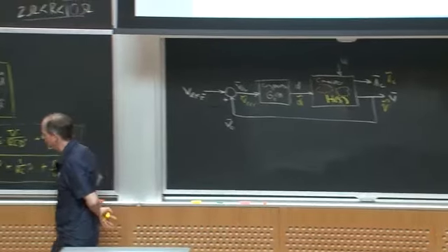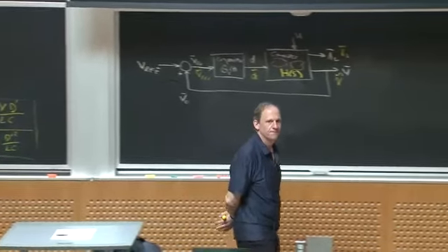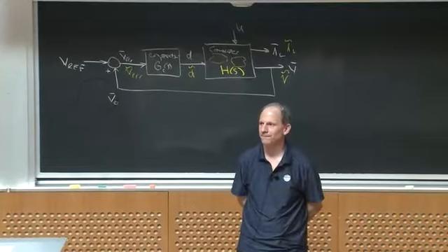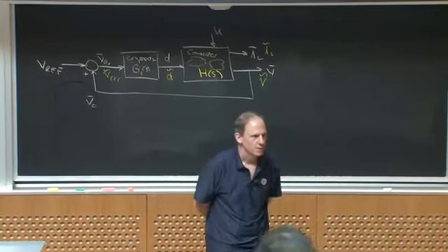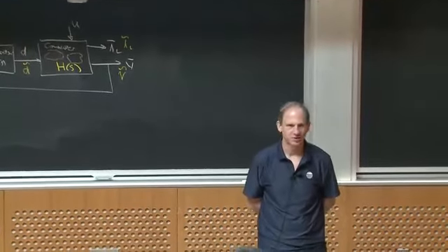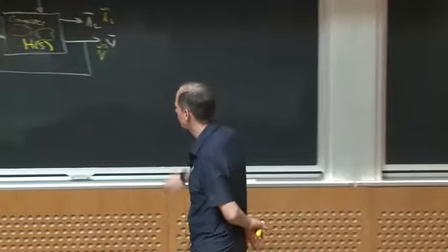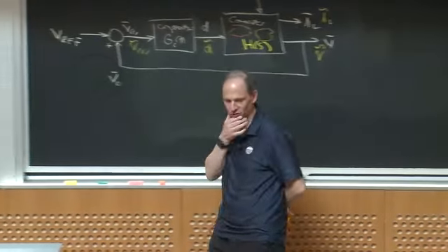These are the steps we covered in the last couple lectures. So I've derived my switched equations, then I've averaged them, then I've linearized them, and now I have a transfer function, and I can start to think about my converter control.